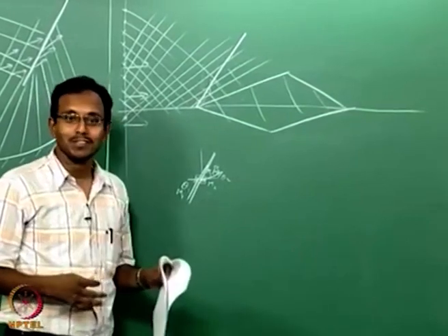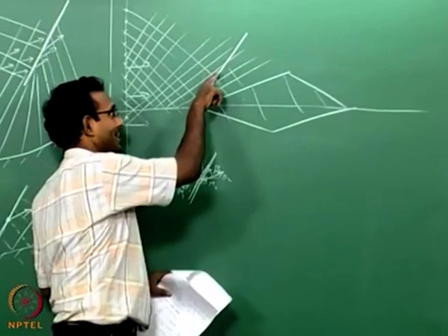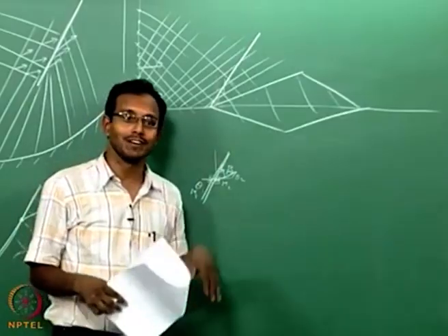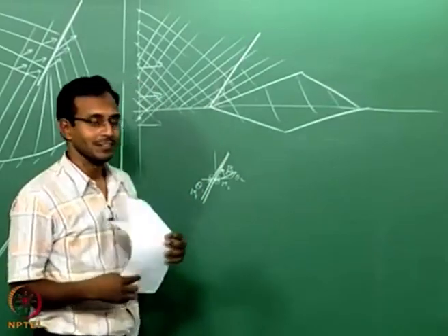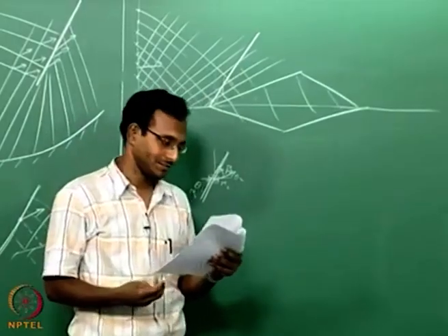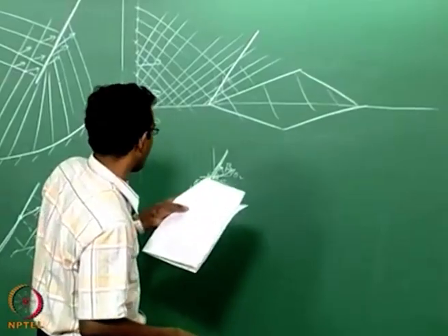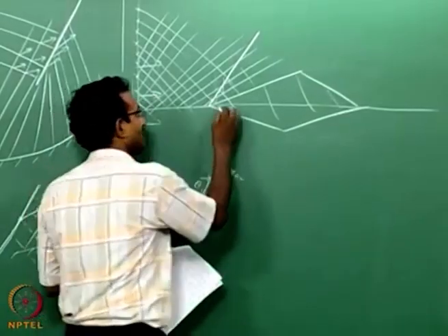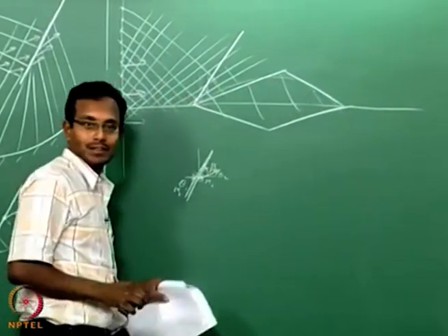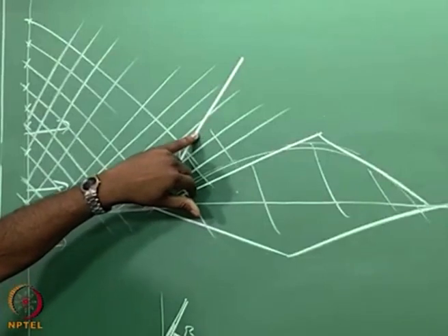Depending on whether the Mach number is very high or not, if you are very close to 1, you can manage having characteristics this way. Most likely you will never have it, always shock will come in and block the left running characteristic. If there is a left running shock, that will cut the left running characteristic typically. If that is the case and I still want to solve the problem, and let us say this is not going uniform, the wedge is some other shape, then there should be a feedback from here to that if I want to solve it.